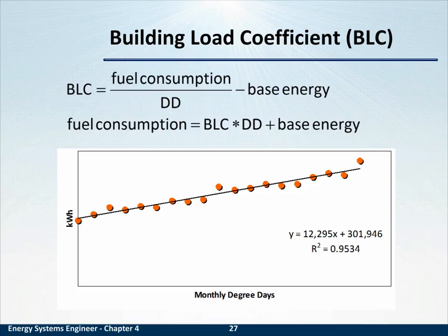Although we don't present every building envelope component and how it can be evaluated, and we focus primarily on the windows, the glass and glazing, we do present the building load coefficient. Annual heating energy use, for a building whose heating is dominated by envelope losses, can be estimated using this building load coefficient method. It's the ability of your building to reflect and react to load and the cost of that energy.